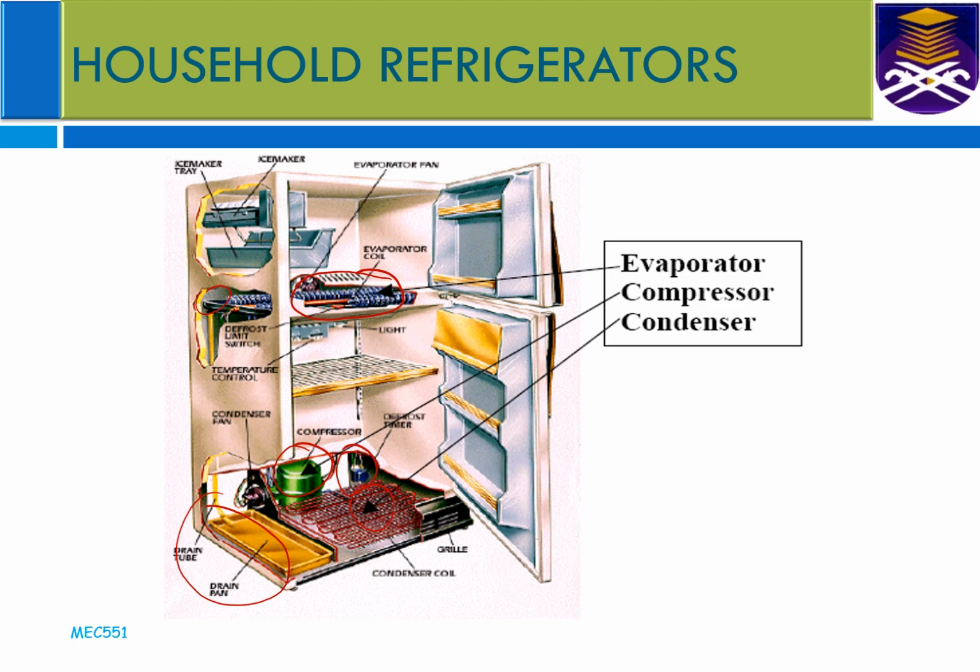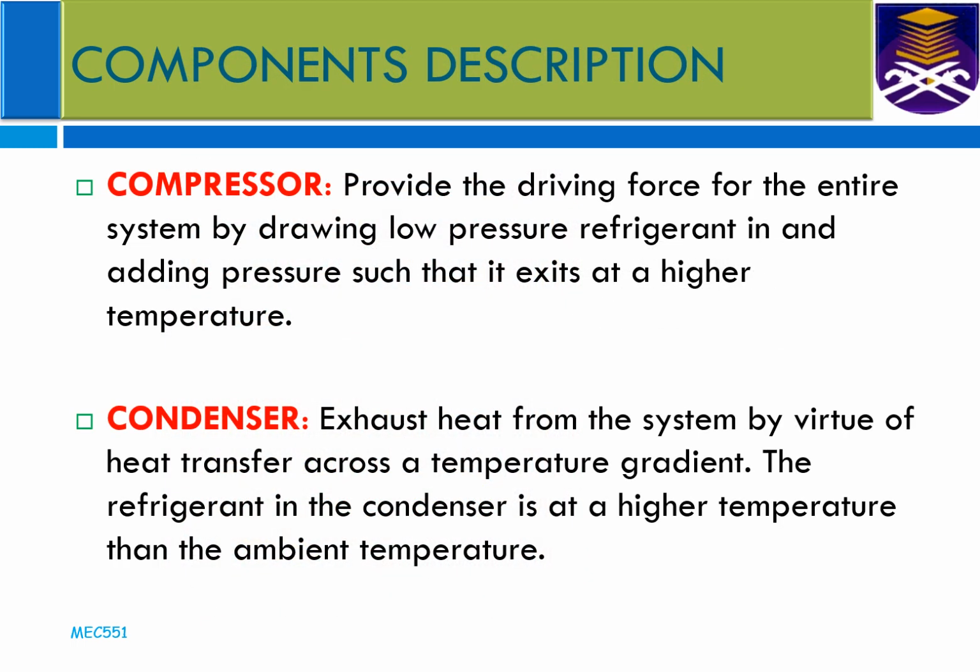Okay, so the household refrigeration system has to contain a compressor, which provides a driving force for the entire system by drawing low pressure refrigerant from the evaporator and compressing it to exit at a higher pressure, and so at a higher temperature, before it enters the condenser.